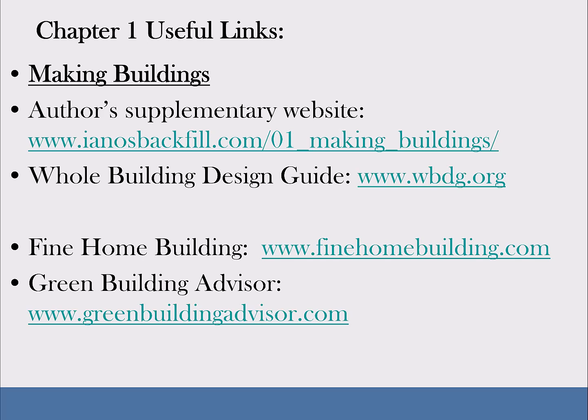Green Building Advisor works at the cutting edge of energy efficiency. There are all kinds of issues that come up, like OSB, that wafer chipboard. It turns out it's not such a solid material. Some brands and some types of that stuff are not sealed well enough, and so air can blow through them. You tend to think you put a board up, you've got a solid surface, and that's not the case. And that was first brought out by the people at Green Building Advisor.